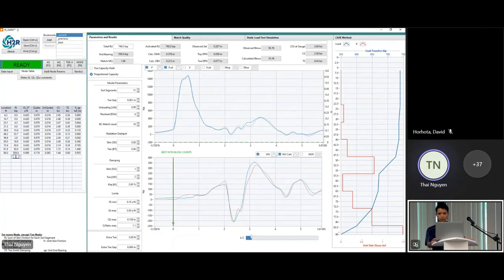So let me hit F6 on this toe, see what it has. If I hit F6, it thinks the best end bearing for this would be 600 kip. Total resistance now matches at the toe. The skin friction is not quite matching yet though.